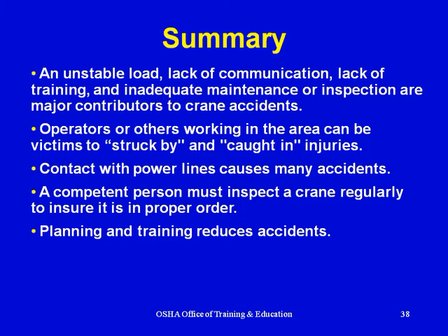In summary, an unstable load, lack of communication, lack of training, and inadequate maintenance or inspection are major contributors to crane accidents. Operators or others working in the area can be victims of struck by or caught in injuries. Contact with power lines causes many accidents. A competent person must inspect a crane regularly to ensure it is in proper order. Planning and training reduces accidents.